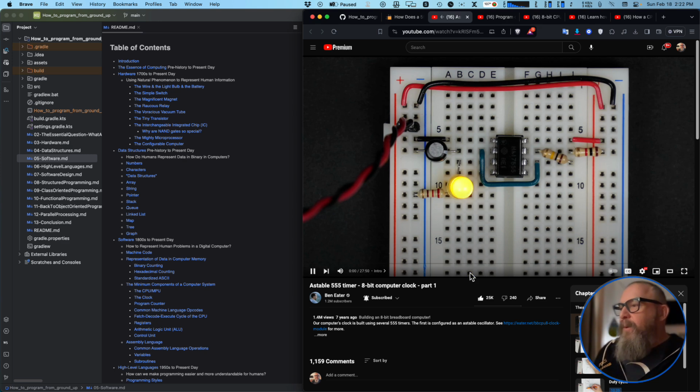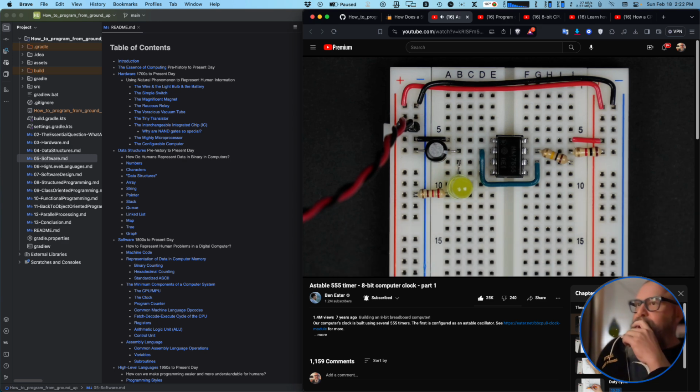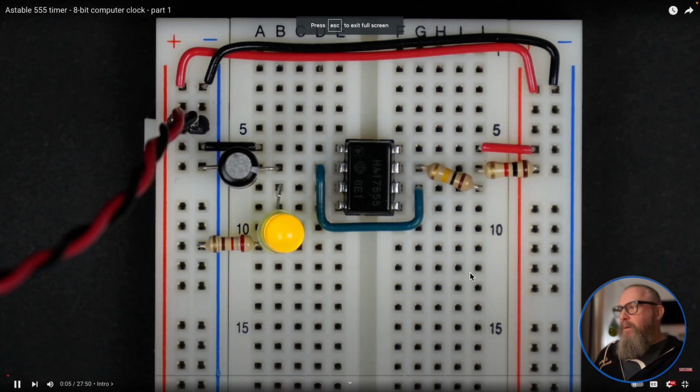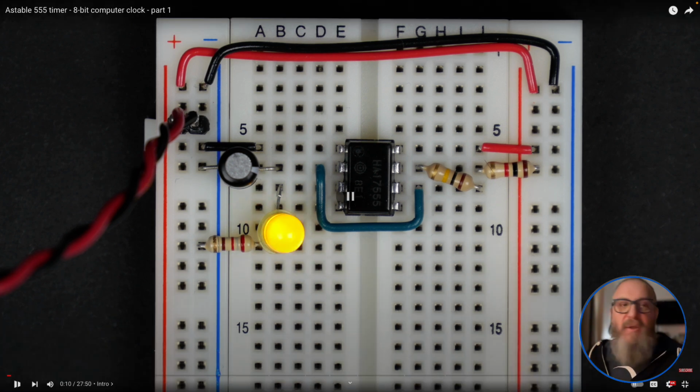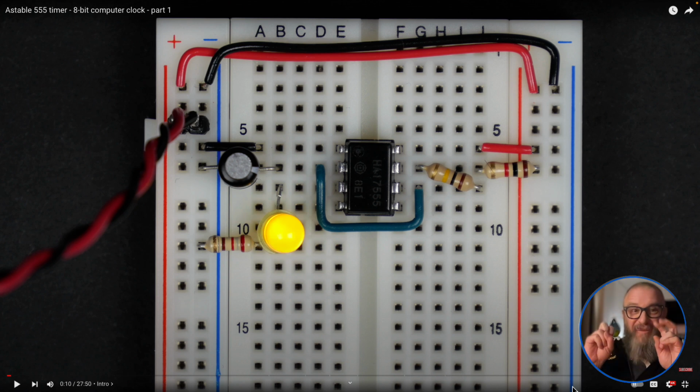So here we go. There are a lot of ways to build a clock circuit for our computer, but we want something that's relatively flexible. We can adjust the speed. We don't want it to run too fast; we want to be able to see what's going on. Adjusting the speed past what the engineers who designed the computer intended is called overclocking. It's just changing the clock speed. You can go up to a point, and then the switches have to switch, and if everything's not synced up properly, it gets crazy. But you can usually overclock it, though it might get a little too warm.